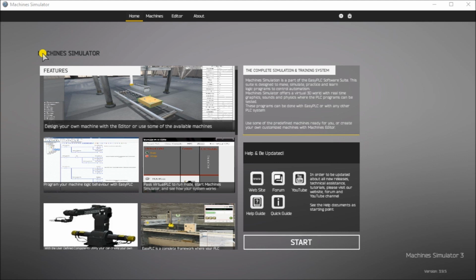We will be developing a Click PLC program for a transfer line, and this is just one of the pre-built machines in the simulators to learn PLC programming. We will be developing the ladder logic, connect via Modbus RTU, and test our program. This involves using the 5 steps to program development.